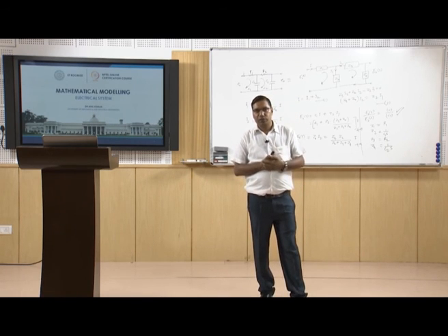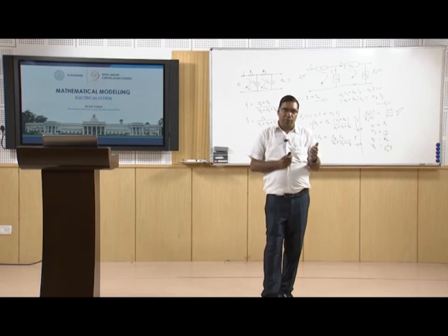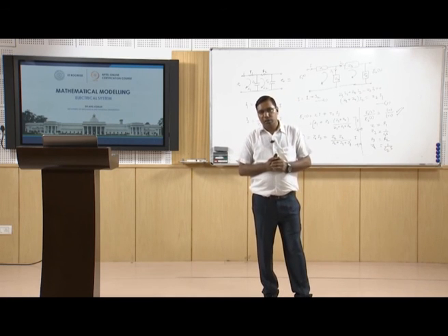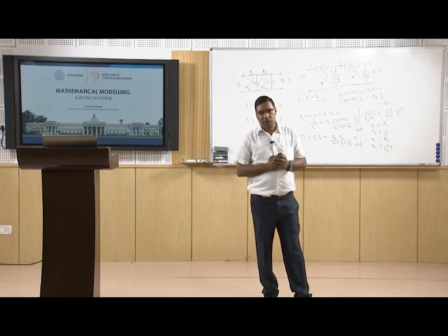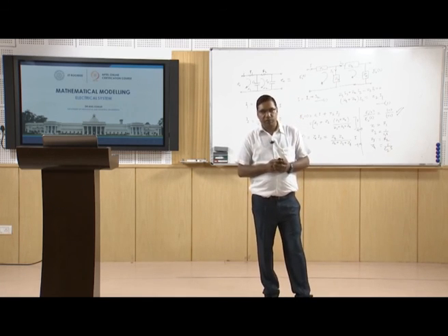First, we write differential equations using Kirchhoff's law, and then we find the transfer function by taking the Laplace transform of that equation. The second method is that we represent the circuit in terms of circuit impedance, and we can directly apply these laws on the impedances, and we don't need to write the differential equations in this case. We can directly find the transfer function.